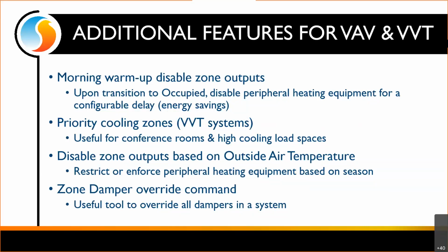So even if the space is comfortable and maybe it's not asking for heat, we're still going to let the hot water valves modulate a little bit to give off a little bit of heat. It's going to create a heat shield, and we're going to slow down the cold from creeping in.